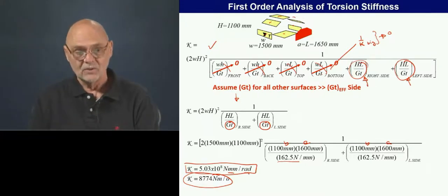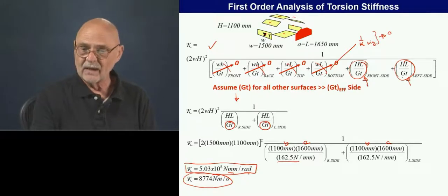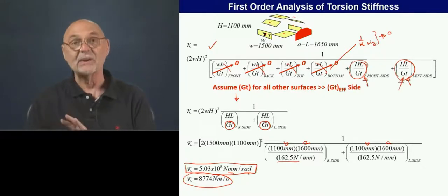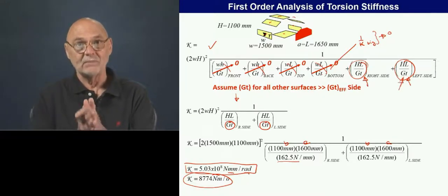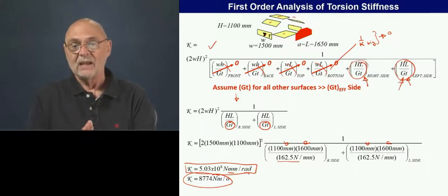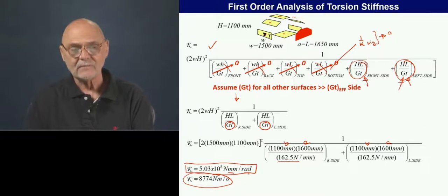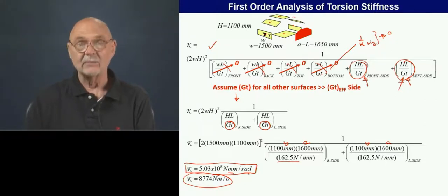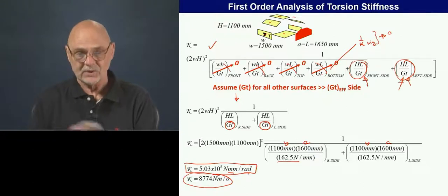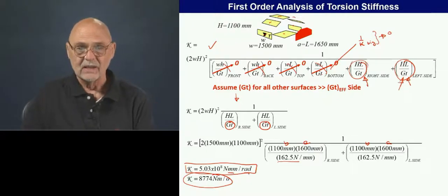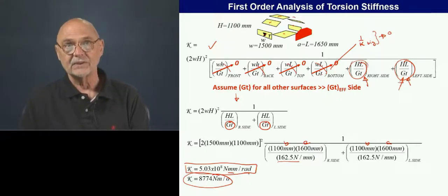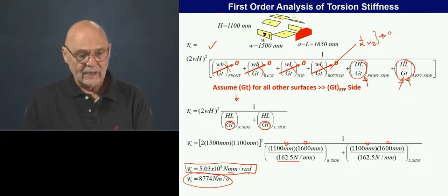So this is how we can really use our little model that was specifically designed for kind of flat shear resisting panels, and use this idea of this little pinned picture frame model to get an effective GT and then plug it into this equation. Okay, so now we have a pretty good calculation method to come up with torsional stiffness of the body structure.